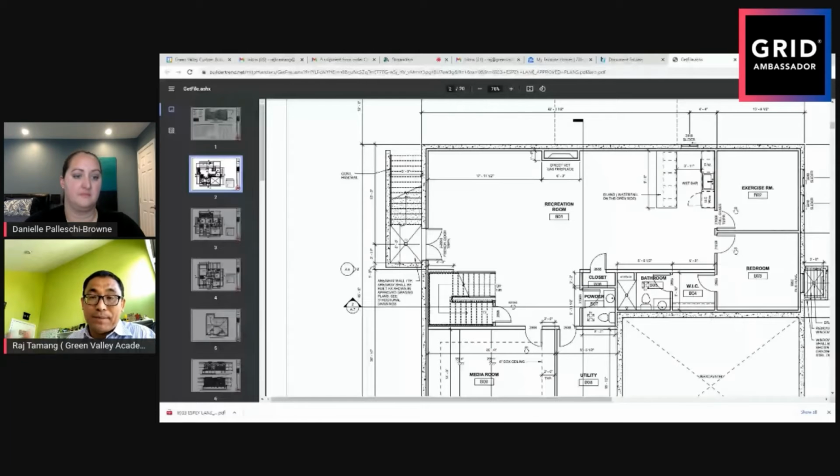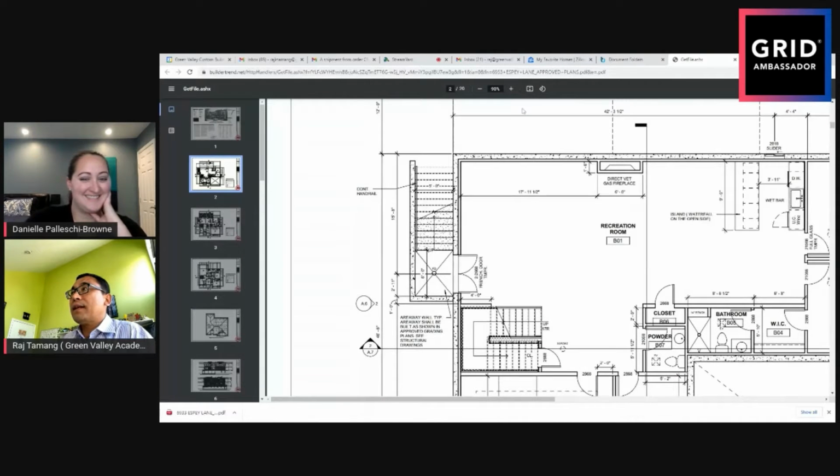But usually if you have a basement, you have access from the basement outside, not coming to the front, maybe on the back or on the side, you have a door. So if you have a door and it's a fully buried basement, how are you going to come out? So you have to make an areaway. So you see in this house, look at this. I have a door. This is the basement. From the door, I'm coming up. So that's the areaway.